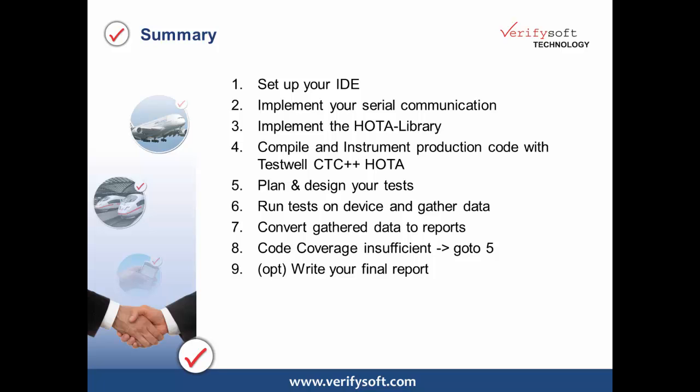After we have a reliable serial communication up and running, we will implement the HOTA library, so it uses the serial communication to send us the data we need to calculate our code coverage. As a last step in the IDE, we compile and instrument our production code with Testwell CTC and HOTA. After we have planned and designed our tests, we have to run these tests and gather this data.